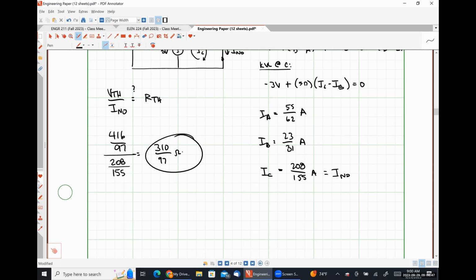I just wanted to show you that if you can find all three, you can check your one. But technically speaking, you only need 2 of the quantities to find the third one. So, like on your exam, I might ask you for the Thevenin equivalent voltage and the Norton equivalent current. And if you can find one of those and the resistance, you can find the answer to the other one without having to do any real circuit analysis, if you so chose. All right, any other questions?